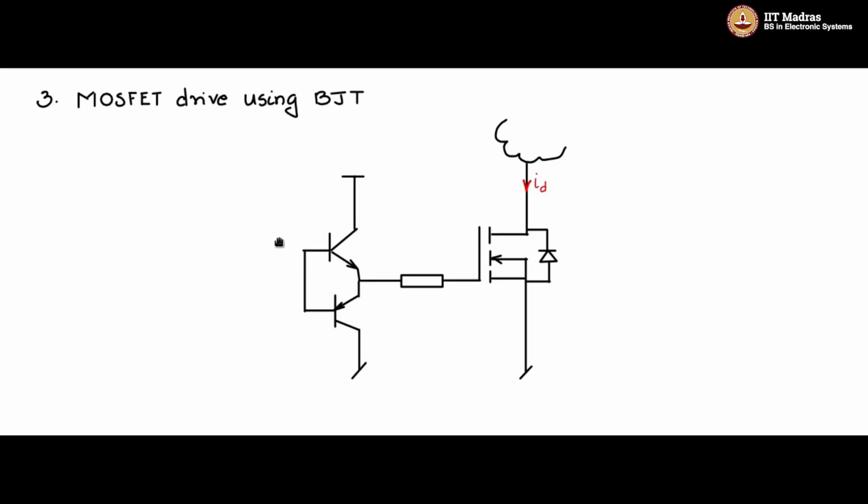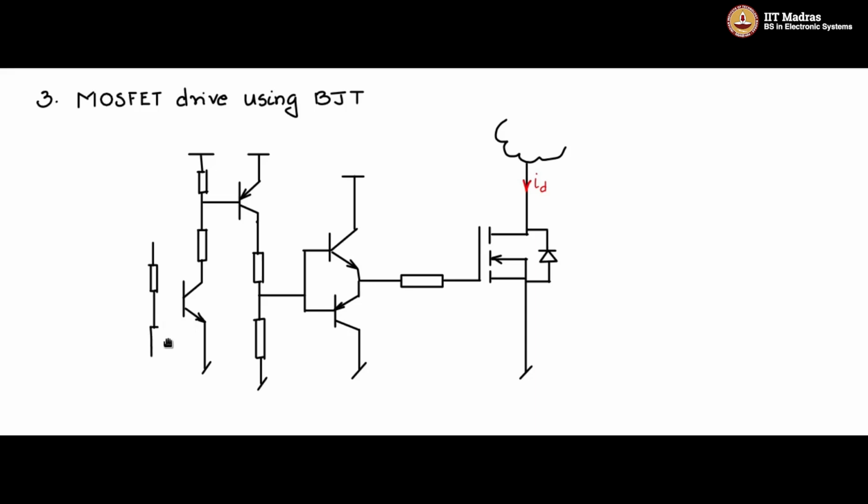and let me connect both the bases together, and let me drive these bases with a 2 resistor base drive circuit, which we are familiar with, and the drive for this is coming from, let us say, a PNP stage. The PNP stage gets its base drive from another 2 resistor drive stage, which is driven by an NPN stage, which is driven by another 2 resistor drive stage. So you see, like this, stage by stage, the current starts decreasing. The current here, the Ig plus, whatever requirement here will be lesser here on the base side of this. On the base side of the PNP, it will be still further lesser, till at the source VB, it can be of the order of microamps to milliamps.